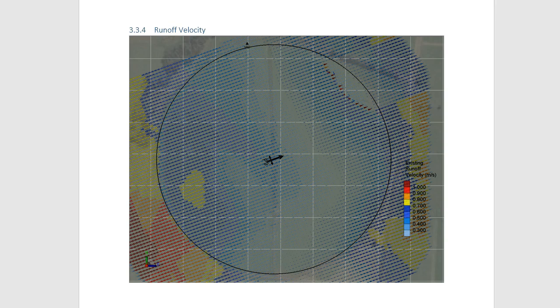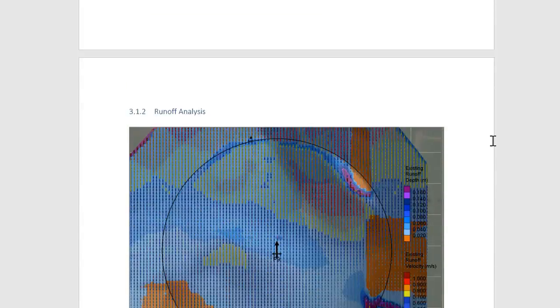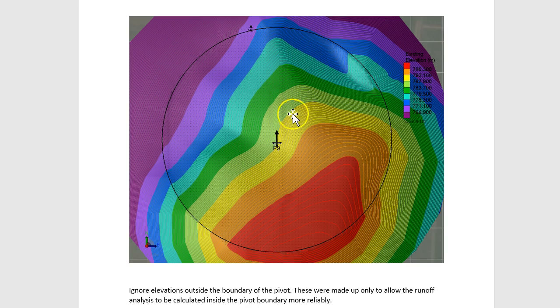We were also asked to provide some feedback on the potential placement of sediment traps, and the comment there would be that this is the lowest edge of the field. There's a natural watercourse going through here, and the erosion risk appears to be, if they continue to run the furrows north-south, here and some here.